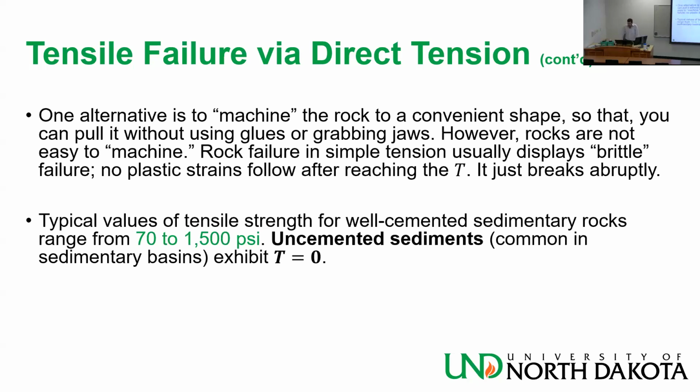Now, uncemented sediments like loose sand, common in sedimentary basins, you don't need to pull them apart, basically you don't have any strength. I don't know if it is realistic to say that T equals 0, but they act as if T is equal to 0.